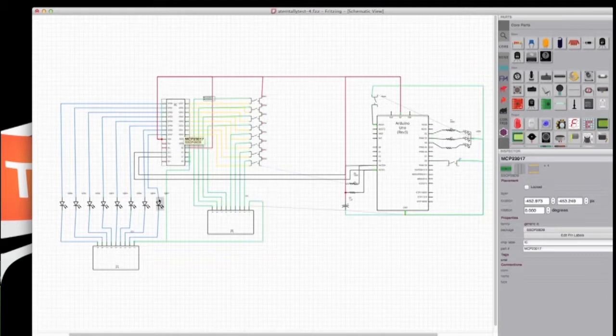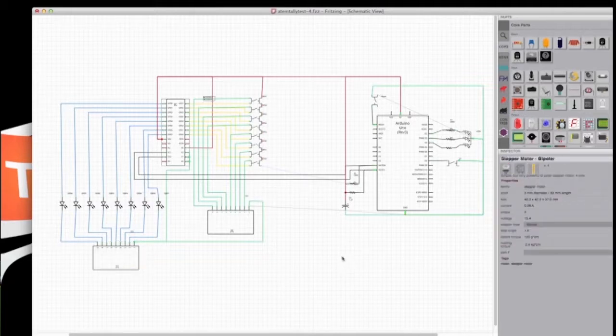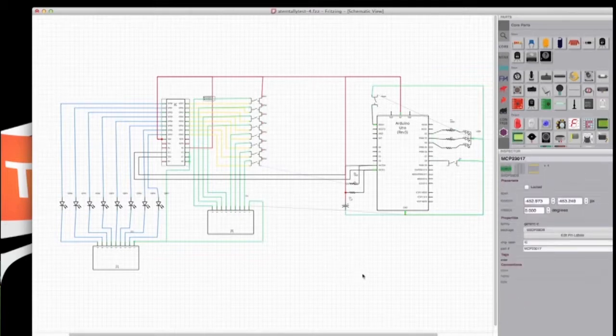And then we have our LEDs right here, and these are actually resistor arrays. That's one of the things about Fritzing: it's not very easy to do things that aren't already in the library over here, and that's something that's really easy to do in Eagle. Of course we have the Arduino on this side. We have buttons here for the input, like we're using the LEDs for the output. This is actually a great board to learn I2C and GPIO.